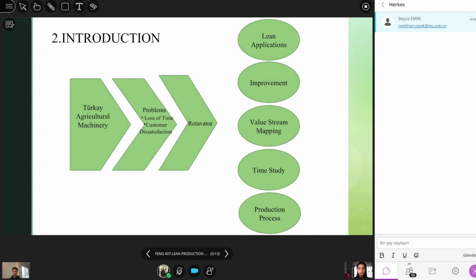Value stream mapping is a lean management method for analyzing the current situation and designing a future situation for a sequence of events that takes a product or service from the beginning of a particular process to the customer. It is a visual tool that displays all critical steps in a specific process and easily measures the time and the volume taken at each stage. It indicates the flow of both materials and information as they go through the process.